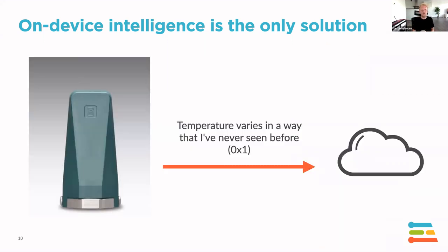And that also means that after that, I only need to drive the radio when I see that something is going on. The fact that my device is sending a message is actually an indication that there might be something wrong. And now we can compress all this data, the hours' worth of, in this case, vibration data, into a single byte, which means that we need to send less often. So we don't need to drive the radio every hour if we only need to send a message when something is wrong. So that saves a lot of power,